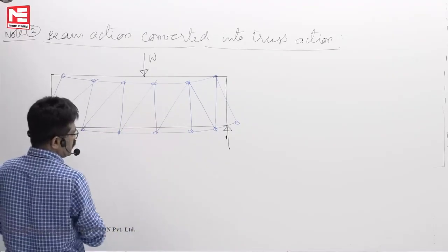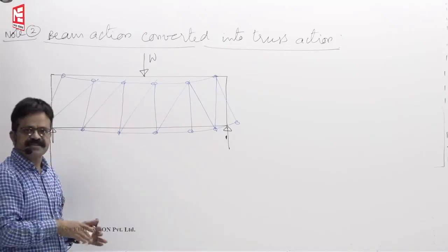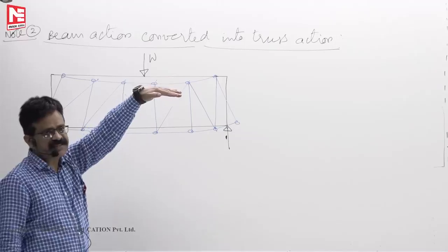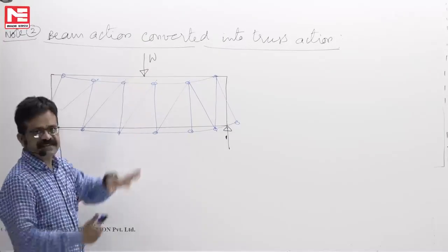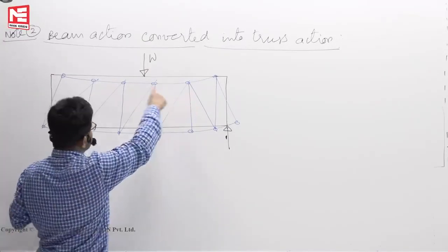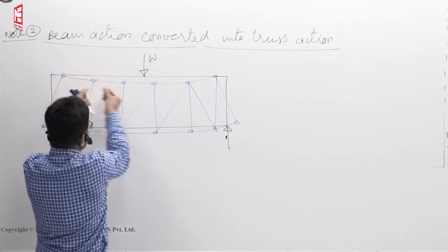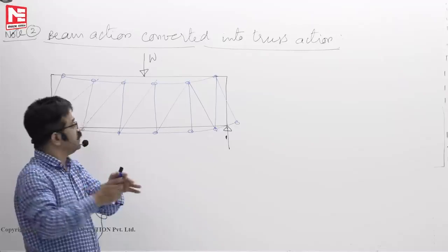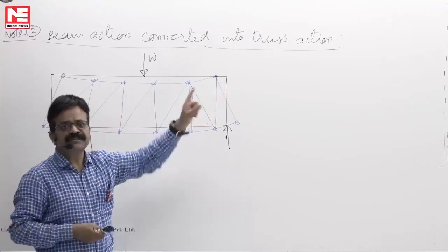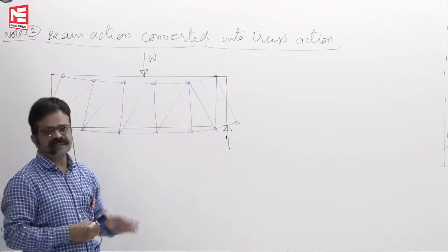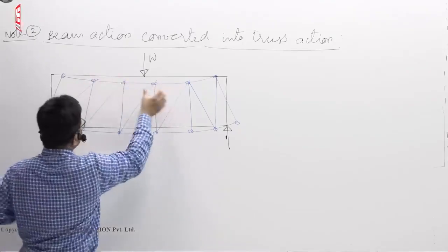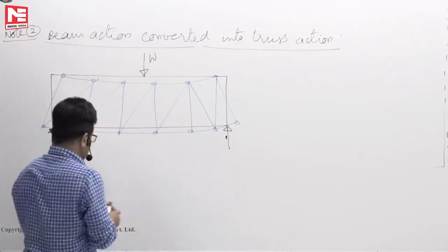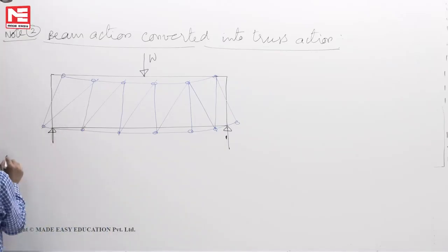Now this is a truss section. Beam is converted into truss. In the process, wherever top fiber you call it as bending stress, now we call it as axial stress. We don't call them as bending stress because you have connected small pieces. Each small piece is subjected to axial force only. That's why length should not be too much. They will bend. Bending behavior again will come like that. So small components, though compression like that will be there. Okay. So this is what happened.